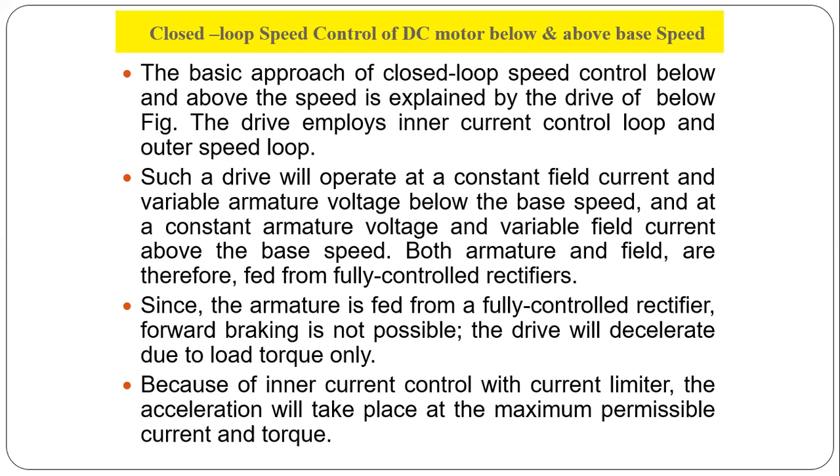Since the armature is connected to a fully controlled rectifier, forward braking is not possible. It is to be noted that in the case of a fully controlled thyristor based rectifier, forward braking is not possible.